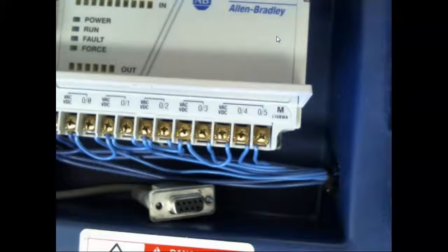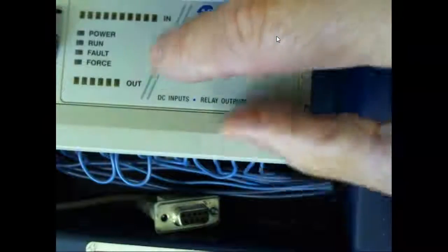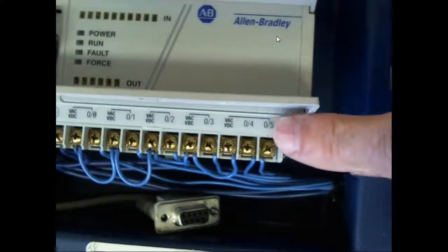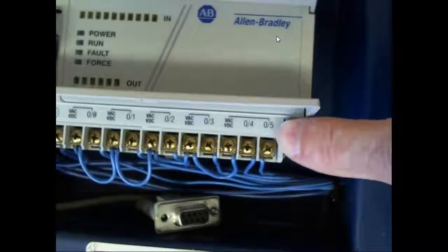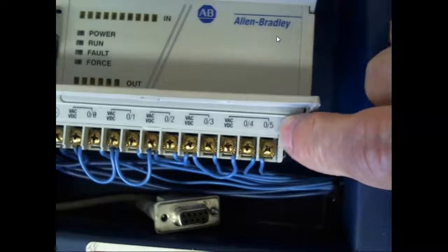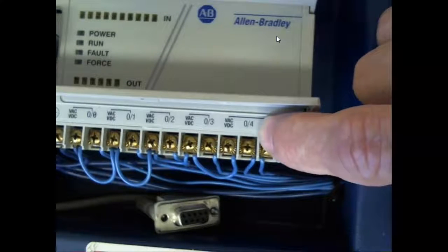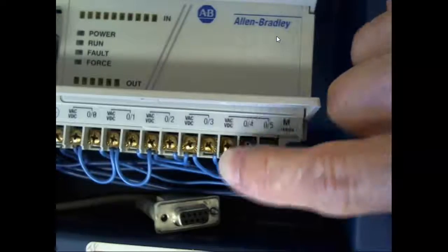Okay. The PLC. I got you. When we say it's got relay outputs, we mean technically the outputs are part of the circuitry built into the PLC. Okay, got you. What's nice about PLC outputs is that we decide what we use as a common. So this guy's got 6 outputs, 0 through 5, and then it's got a common for every one except for 4 and 5, which looks like it shares the same common. I need to look at that.